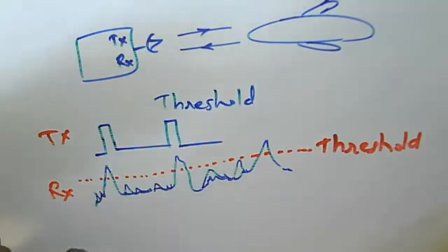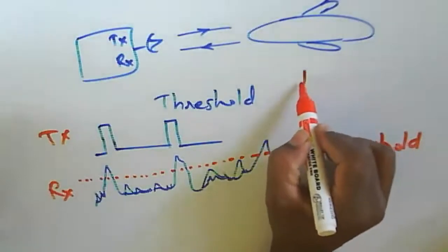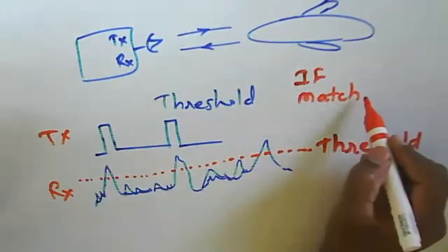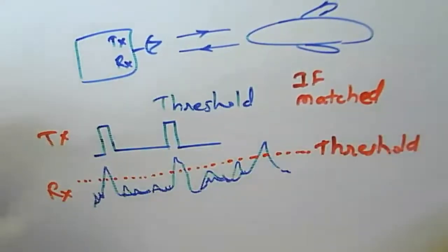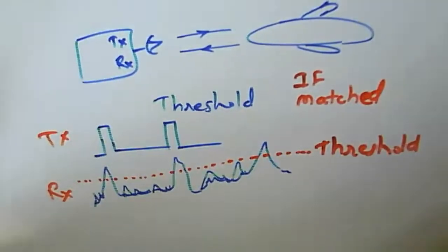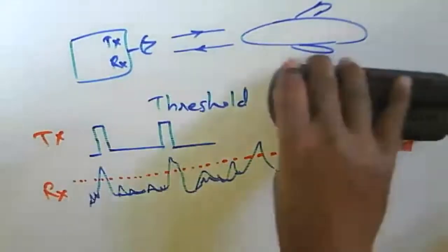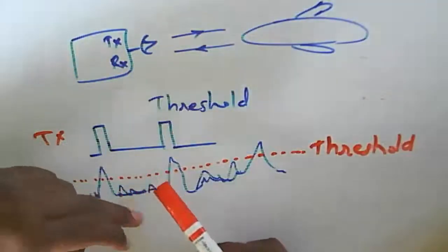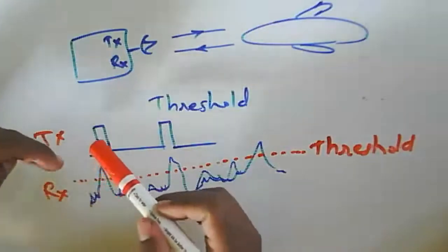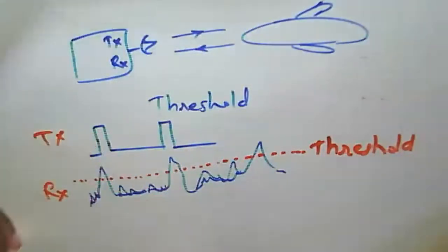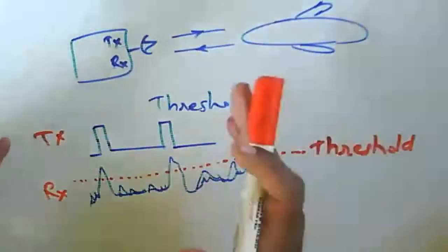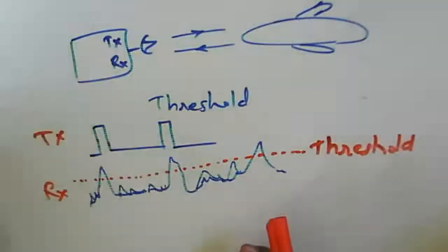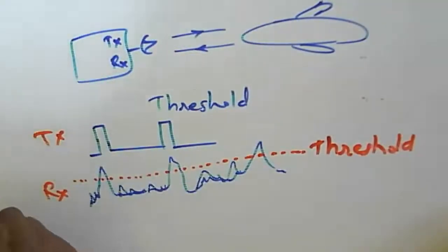We considered the earlier block diagram with the IF, then a matched filter. Now the role of that block is the IF amplifier, so that block amplifies the level of the signal. In that case it will increase the level of the noise also, as well as the level of the signal. Then for a given distance, we find out the minimum detectable signal. That is our role.